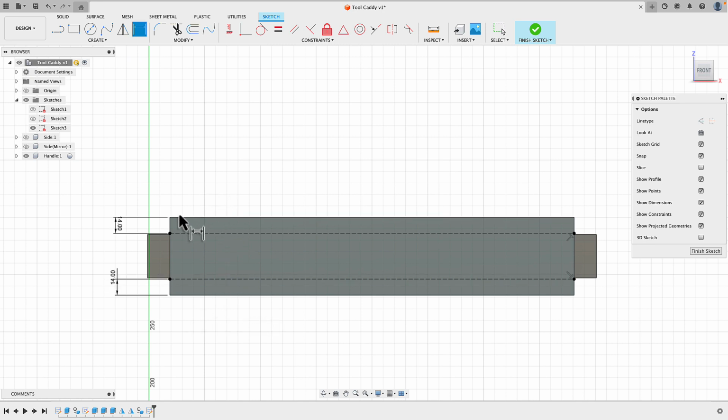The other thing too is when I'm going to create a curve on this, but I don't want to go all the way to the very end here because particularly, in the manufacturing process, depending on how it's cut, it might chip out here, and you want actually this shoulder here to be quite nice and square. So I'm going to go L for line again, and I'm just going to set up a vertical line, another one down here, and construction lines again.